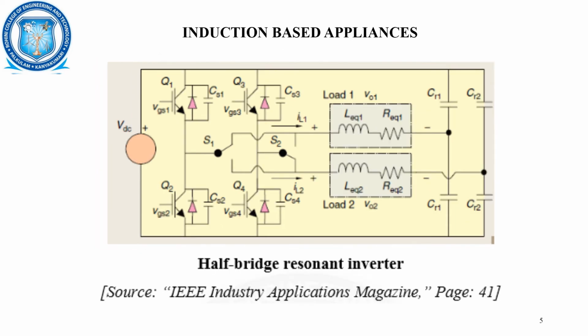In case of half bridge, it is nothing but a capacitor. So in half bridge, it purely depends upon the charging and discharging effect of the capacitor, and this is the difference between half bridge and full bridge. Under full bridge resonant inverter, we have complete control over the switching operations, unlike half bridge. But in certain cases, for economic operation, the switches may be removed and capacitors may be placed instead.